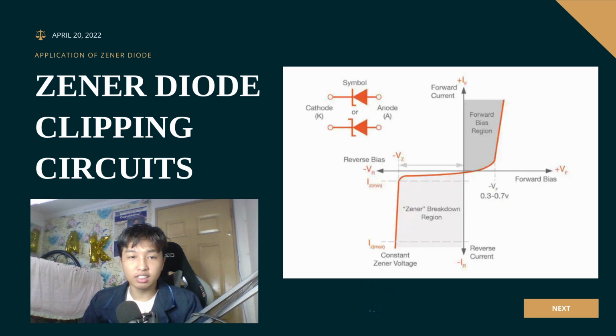The last type of clipper is biased positive clipper and biased negative clipper. When a diode conducts, the negative half cycle of the output waveform is kept to a level of V bias plus 0.7 volt by reversing the diode and battery bias voltage. By adjusting the bias voltage of the diodes, a variable diode clipping or diode limiting level can be achieved.